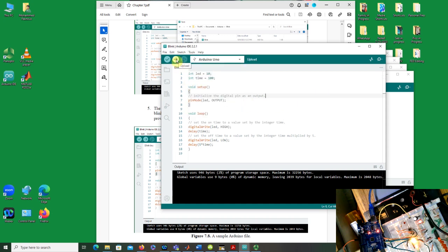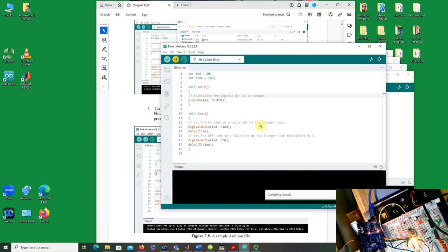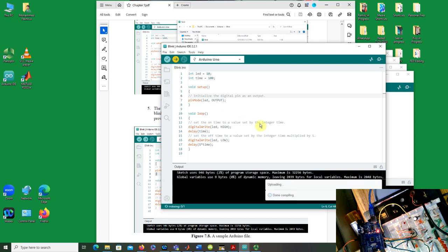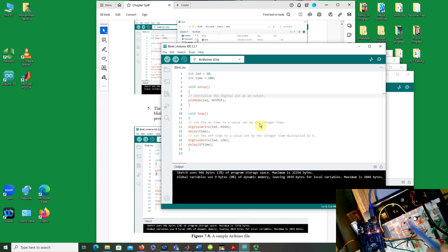And so when I upload it, I go to this arrow, the left to right arrow, that's uploading. That means the program will be transmitted into and stored in the microcontroller, and it will run automatically. So at some point, as you will see, everything stops, and as you see here, this LED, which is of course protected by this resistor, in this case a 100 ohm resistor, it doesn't matter, somewhere between 100 to 470 ohms.